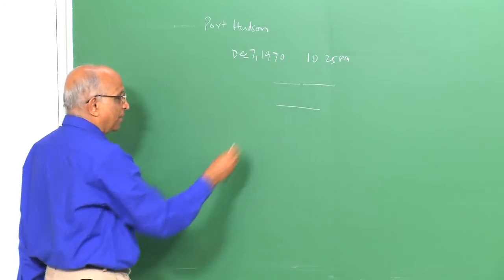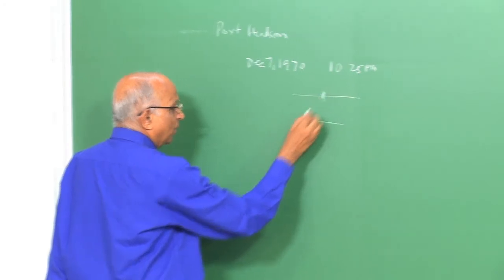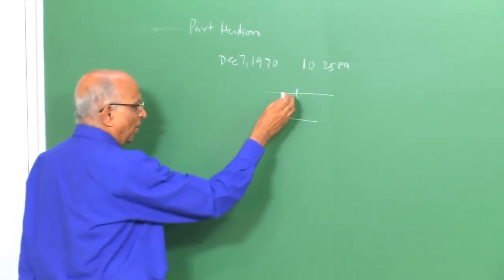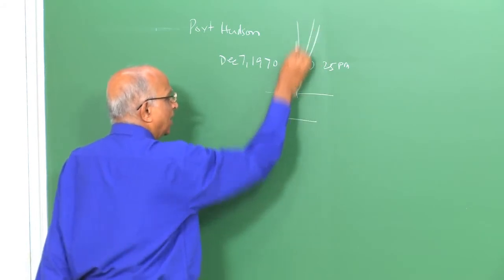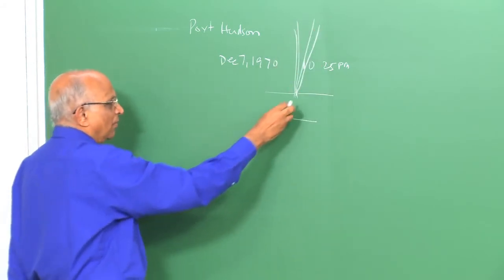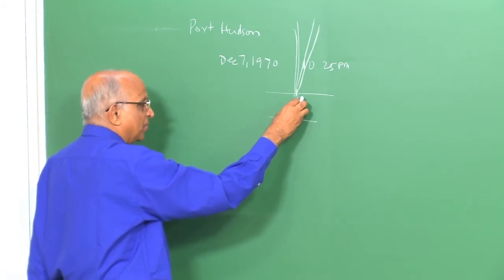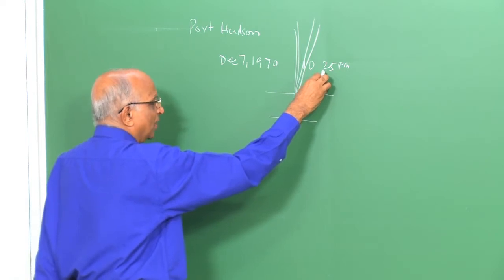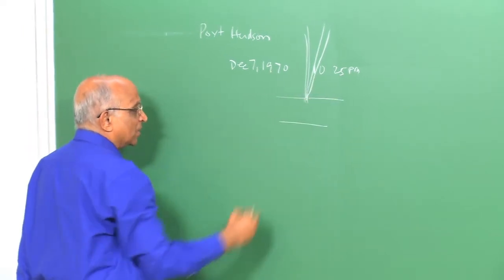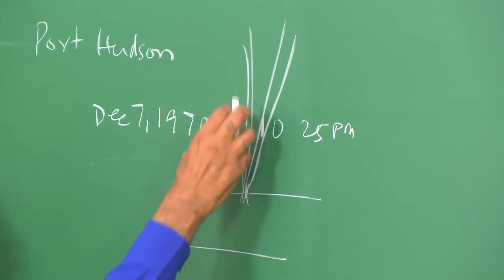The propane was at high pressure, around 65 bar. It opened at one of the welding joints, and you had a huge fountain of liquid propane. Liquid propane at high pressure is stored as a liquid at ambient temperature. But at the ambient pressure of 1 atmosphere, it boils at something like minus 43 degrees centigrade, and therefore it immediately flashes into vapor.